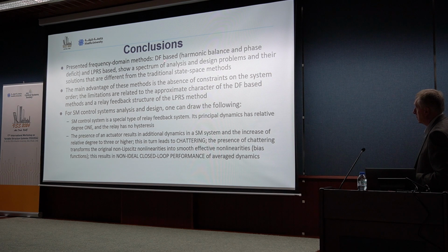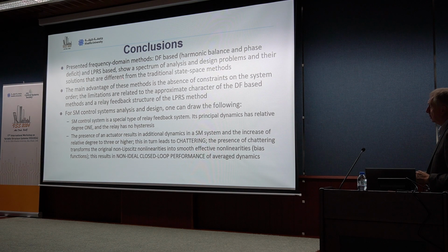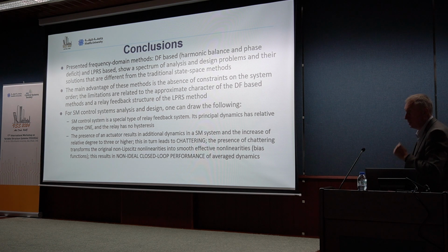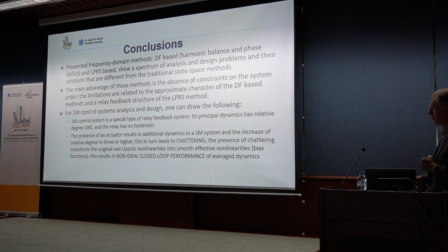The presented frequency domain methods, DF-based, harmonic balance, phase deficit, and LPRS-based, show a spectrum of analysis and design problems and their solutions that are different from the traditional state-based methods. The main advantage of the presented methods is the absence of constraints on the system order, so it's any order of the system. And the limitations are related to the approximate character of the describing function based methods and the relay feedback structure of the LPRS method. So it's only relay feedback structure.